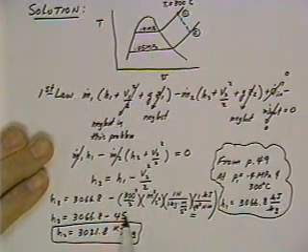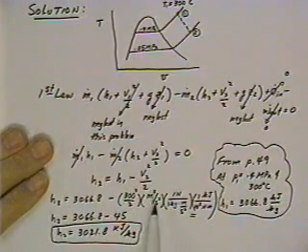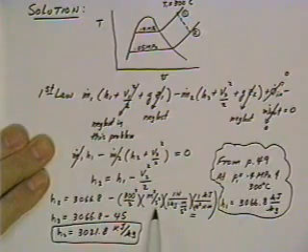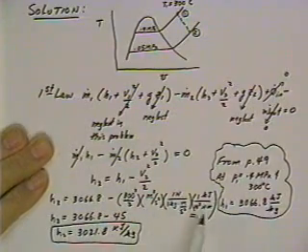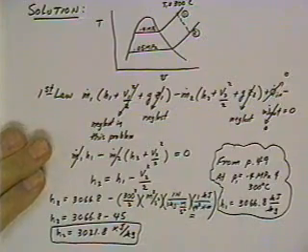So if you're not familiar with the conversion here in kinetic energy, you ought to work out some of them just to make sure that you've got the right units. Meter squared per second squared does indeed convert to kilojoules per kilogram if you run through the normal conversion here, and make sure you include the 1,000 Newton meters per kilojoule.